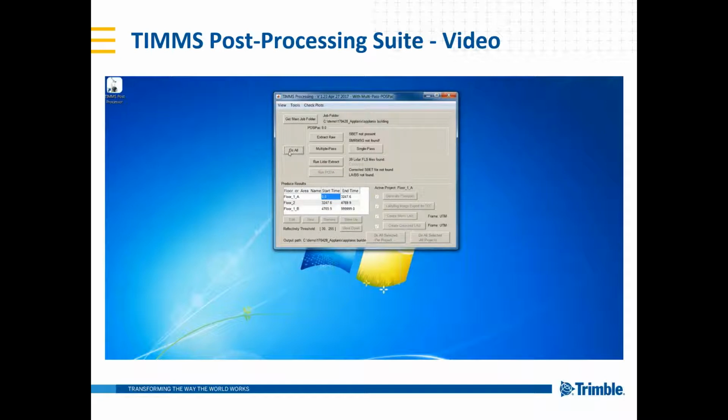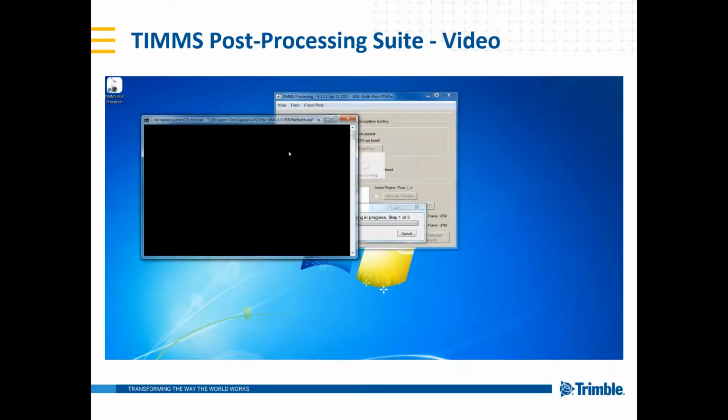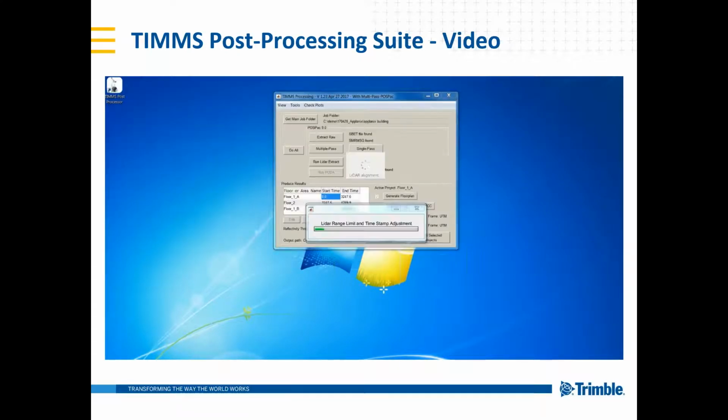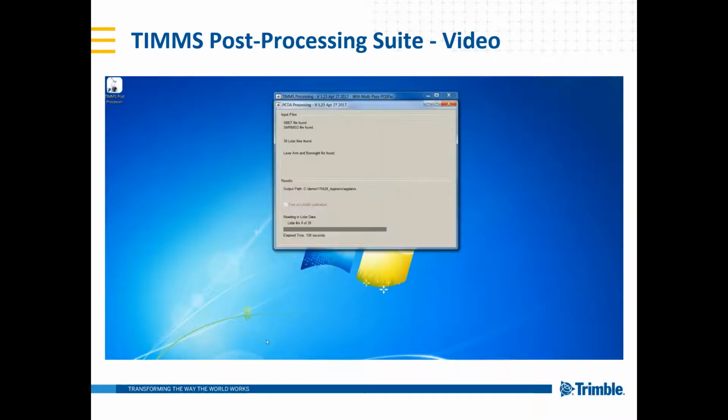All of the data is georeferenced. Because we've got those control points, which are latitude, longitude, everything else from this point on is georeferenced to those points. So the LAS is georeferenced, and the rasterized image and all of the exterior orientation. You're getting latitude and longitude coordinates for everything.